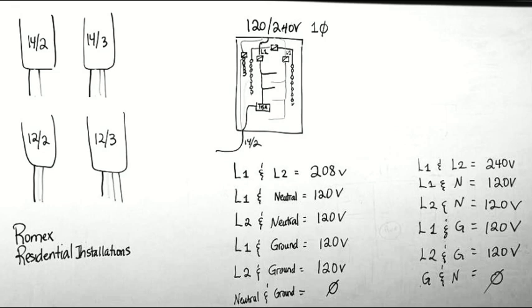So for example, if I apply 120 volts to this circuit, which is the nominal voltage that we have in a home, resistor number 1 is going to receive 120. Resistor number 2, 3, 4, 5, 6, 7, 8, 9, and 10, all of them are going to be receiving the same pressure. So all of them will work at 120 volts.